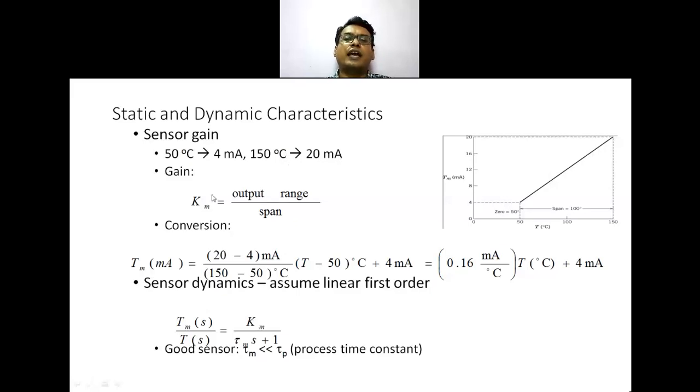And accordingly, I will keep the ranges by using a certain formula so that the sensors will be calibrated accordingly. Similarly, if I want to measure level from 0 to 100%, I will use 4 to 20 milliamperes: for minimum level 4 milliamperes, for maximum level 20 milliamperes, and in between, if 5 milliamperes is the current, it has to be calibrated, all these things.